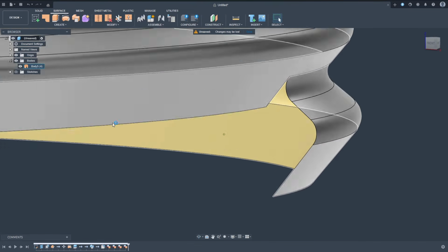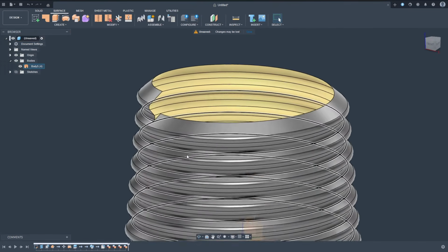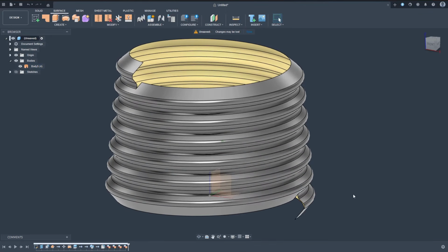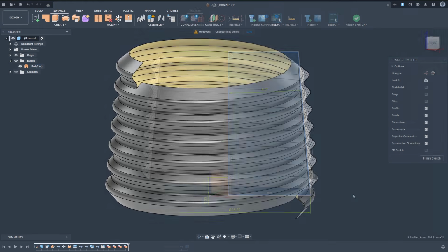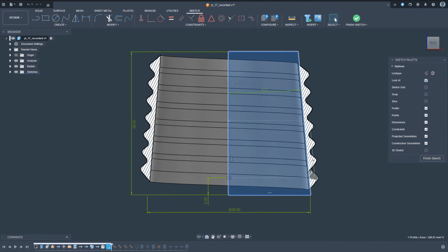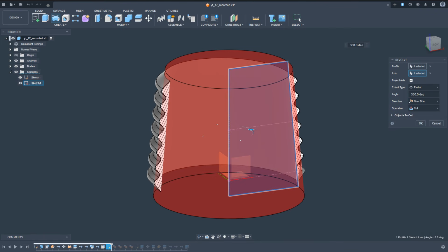It might happen that the surface topology of your thread part is more complex, and it would be tedious to select all faces to remove. In this case, you could try to change the sketched profile as mentioned before. Another solution might be to create a new sketch and sketch a quadrilateral similar to the very first sketch, like shown here. Then you could create the revolve, which cuts away the inner topology as shown here, resulting in one single face to remove.